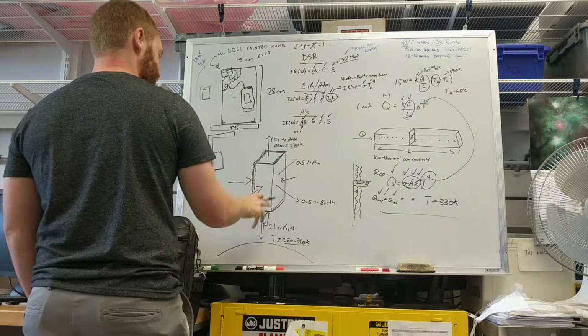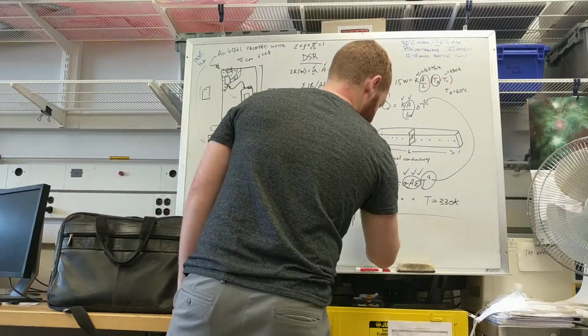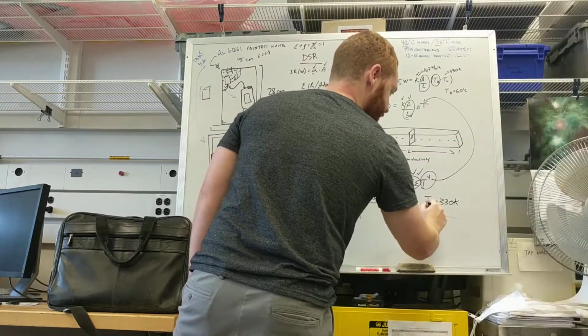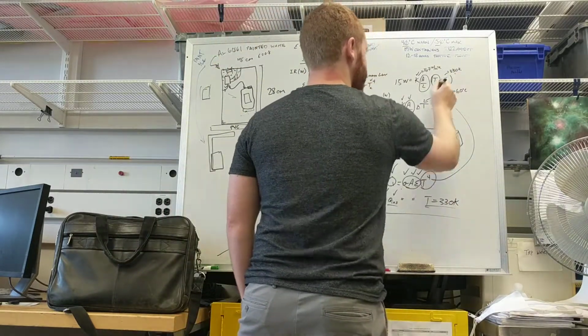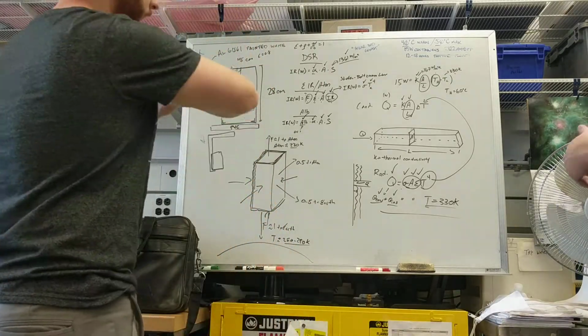You take a look at what's going on. You do a radiation analysis to take into account the environmental load and what I'm trying to dissipate. What's the temperature of the surface? And then once I've got the temperature of the surface, I can figure out what the temperature of my electronics are going to be. So that's how you back everything out.